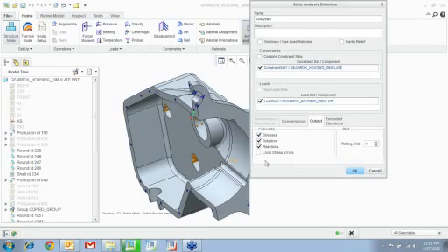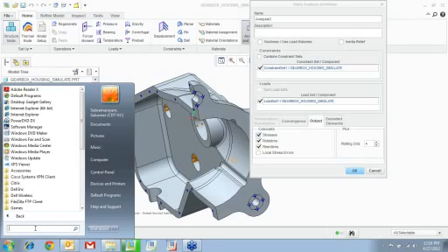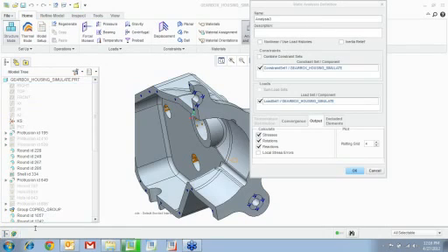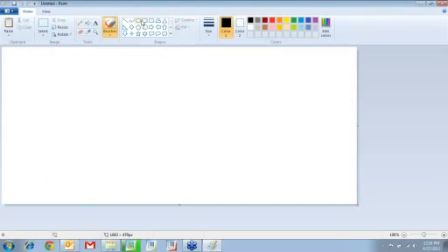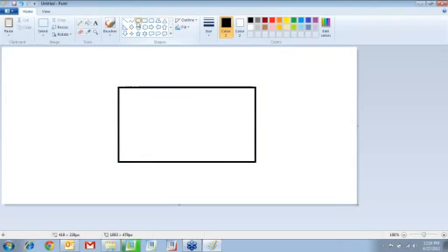In the output, you see that you have stresses, rotations, reactions. There is something called plotting grid. Now, what is a plotting grid? Let me just use Paint, which is my favorite tool, and I can show you guys how it works. Now, let's say we have a plate and we have a hole. All right. Now, ProEngineer uses P-type FEA. P as in parametric. Okay.